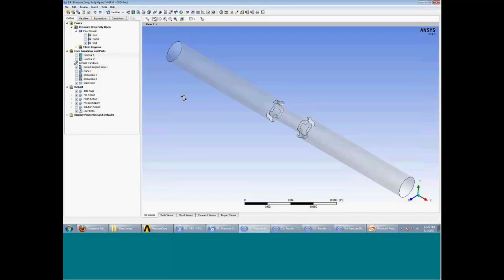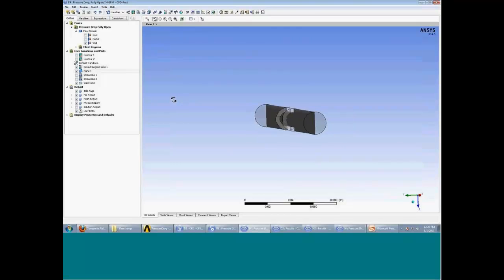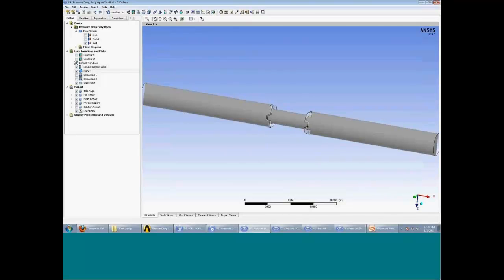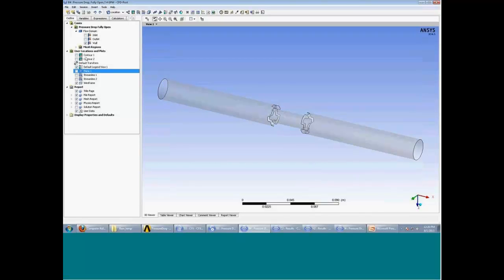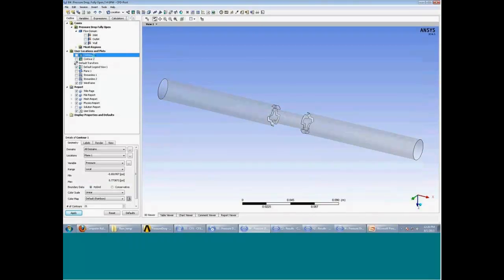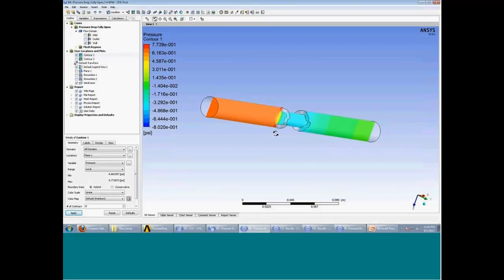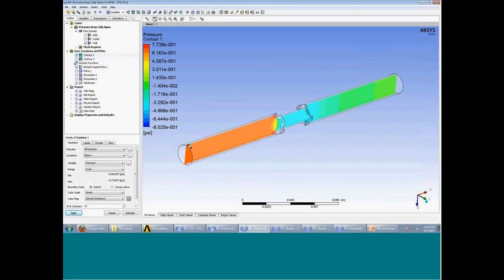To look at the pressure, what I do is first take a section through the flow domain, create a plane, and in this plane, I can plot the pressure values. So I plot the pressure values. You look at it, and you can see that at the outlet, you're looking at the relative pressure, so the pressure is 0, and at the inlet, you have a higher pressure.